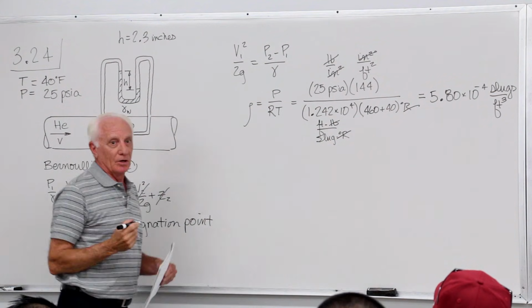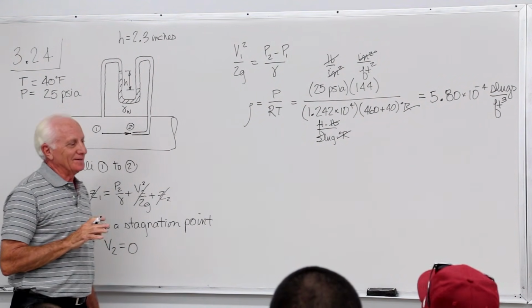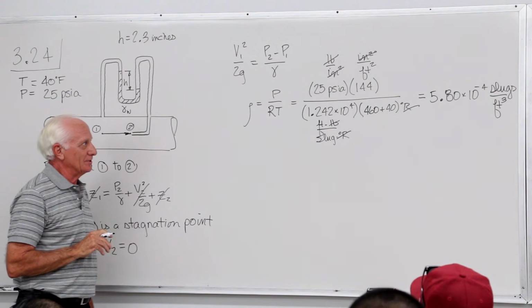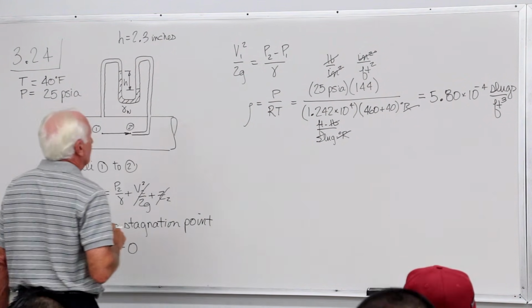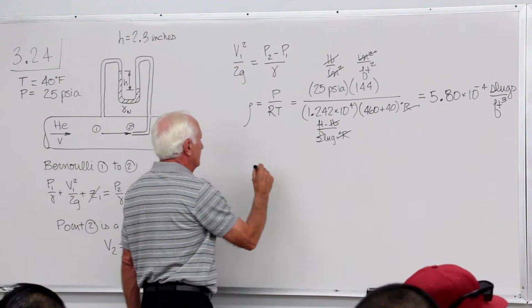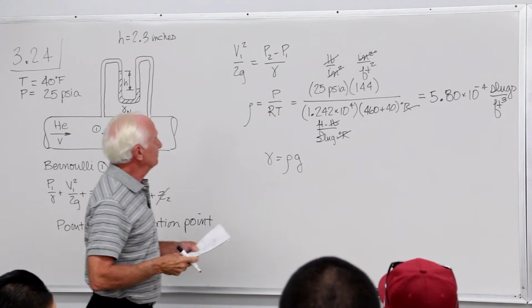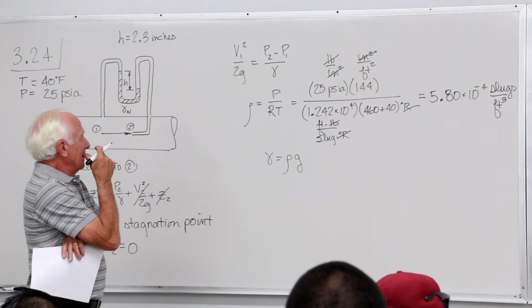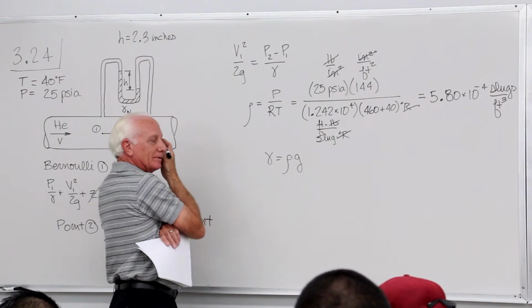There you have it. But always check your units, because that sometimes is what makes the big difference, if you don't check the units. Always check the units to make sure it's going to be right. Okay, we have rho. We need gamma. So gamma equals rho g. I'll replace that with rho g up there. What's left? Well, there's another g right there. They're going to cancel out anyway.